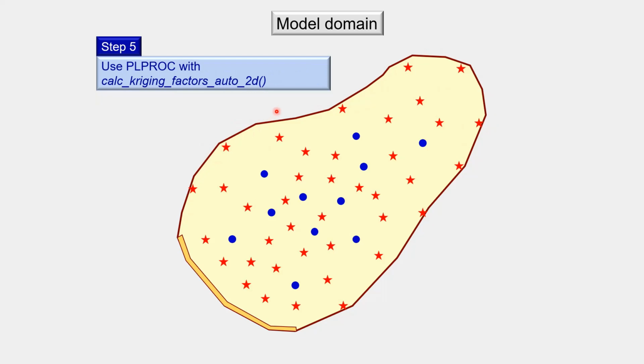And then I will use one of those Proc functions that we discussed previously. I normally use this function these days to undertake the interpolation from the pilot points to the model grid, this accommodating the fact that I have differential spatial densities of pilot points in different parts of the model domain.